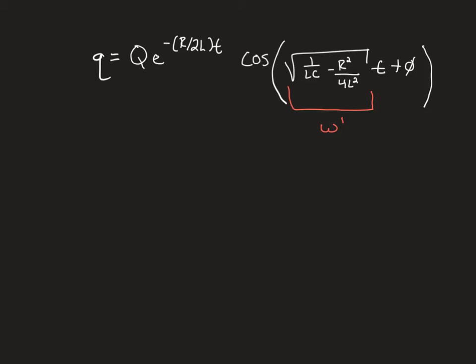Now, the amount of resistance in the resistor dictates how that oscillation between the capacitor and the inductor will go and how long it actually oscillates for. So if the resistance is very high, then you run into an issue where it never really oscillates. The energy just dissipates through the resistor and you don't really get another cycle. But we're going to talk about realms where R is relatively small so that we can actually see a reduction in the amount of oscillation.